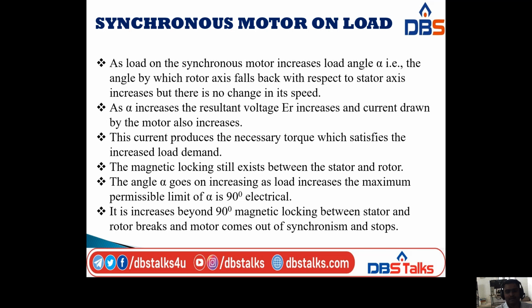Next, the magnetic locking still exists between the stator and rotor. The angle alpha goes on increasing as load increases. The maximum permissible limit of alpha is 90 electrical degrees. Up to alpha equal to 90, we have magnetic locking between stator and rotor. When alpha increases beyond 90 degrees, the magnetic locking between stator and rotor breaks, and the motor comes out of synchronism and stops.